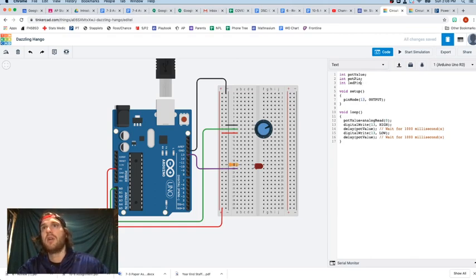For example, if you want to change a pin and you have it written 19 million trillion times, so let's say your program's a couple hundred lines long and you want to change all of the ones that are 13 to 9, instead of going through your program and having to change them all manually, just give it a name and change it once. So int LED pin equals 13. And then down here, I'm going to plug in LED pin and LED pin.